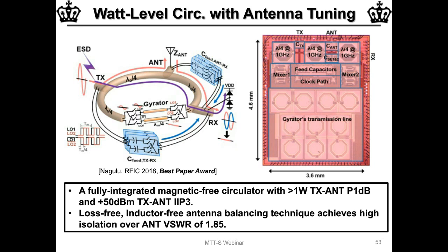Generally, in terms of CMOS circuit design, over time, the community has figured out good ways to isolate different nodes of a circuit or different wires within the layout. We use best practices there: if you want two things to be isolated, make them as orthogonal as they can be to each other, and use ground shields everywhere as much as possible. Here, this is an SOI CMOS process where most of these circulator works are done, and so the lack of a conducting substrate helps somewhat as well.